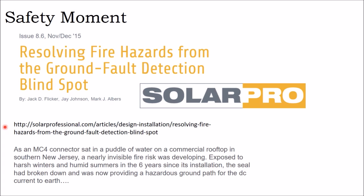And let's just read the description for a minute describing the Dietz-Watson warehouse fire in New Jersey. So you can read the whole article on Solar Pro, great magazine for solar professionals, obviously. But as an MC4 connector sat in a puddle on a commercial rooftop in New Jersey, a fire risk was developing. Exposed to harsh winters and humid summers in the 6 years since its installation, the seal had broken down and was now providing a hazardous path for the DC current to Earth.